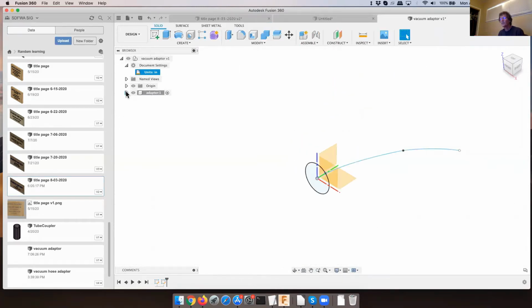Now this sketch, when I look at my sketches, sometimes it gets confusing about which sketch is which. So what I like to do sometimes is name them. So you can actually rename these sketches. So sketch 2, I'm going to call the spine. Sometimes I'll put more features on this and call it a skeleton, but in this case, it's really just a spine. And this sketch I could rename if I wanted to as well, and I'll just call it large end.